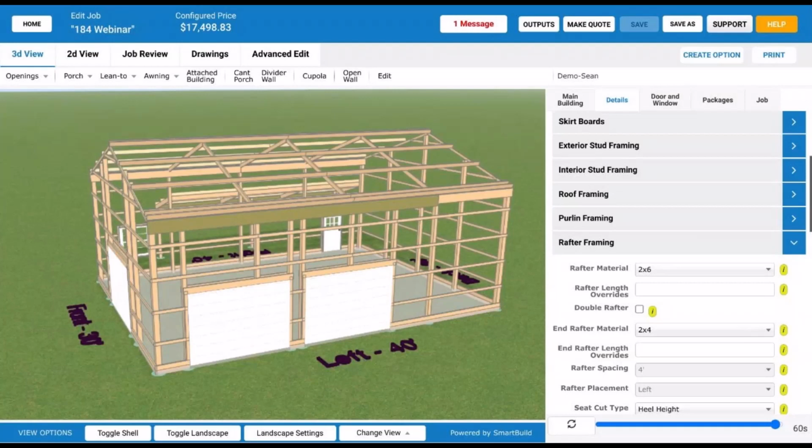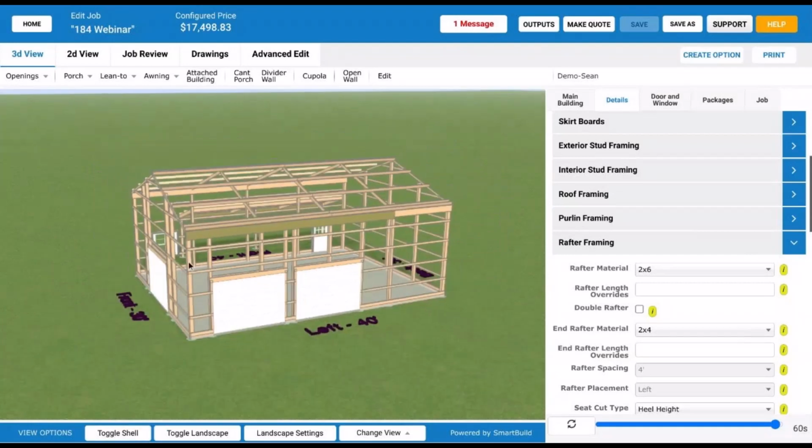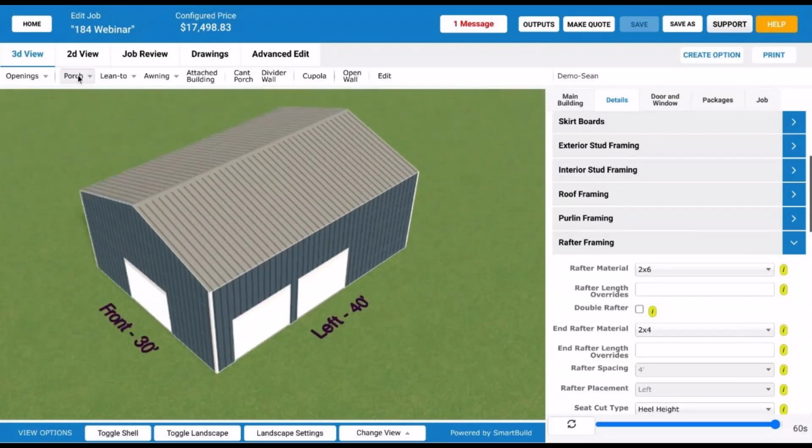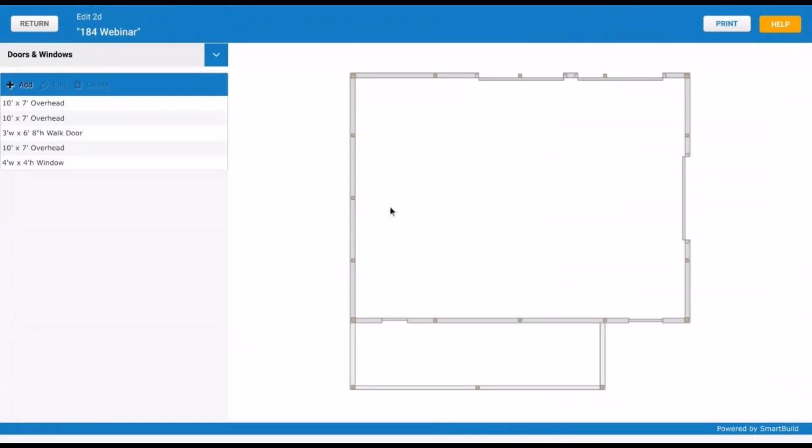Did you talk about the 2D and 3D issues? No. Yeah, that's a good point. So in preparation as well for the interior walls, we have this 2D mode that you can switch over to. This allows you to quickly put in doors and windows. What we did in this release, and this was a big change, so thanks, Paul, for bringing this up, is we basically tried to make the 3D and the 2D consistent in the way that these work in terms of the input.